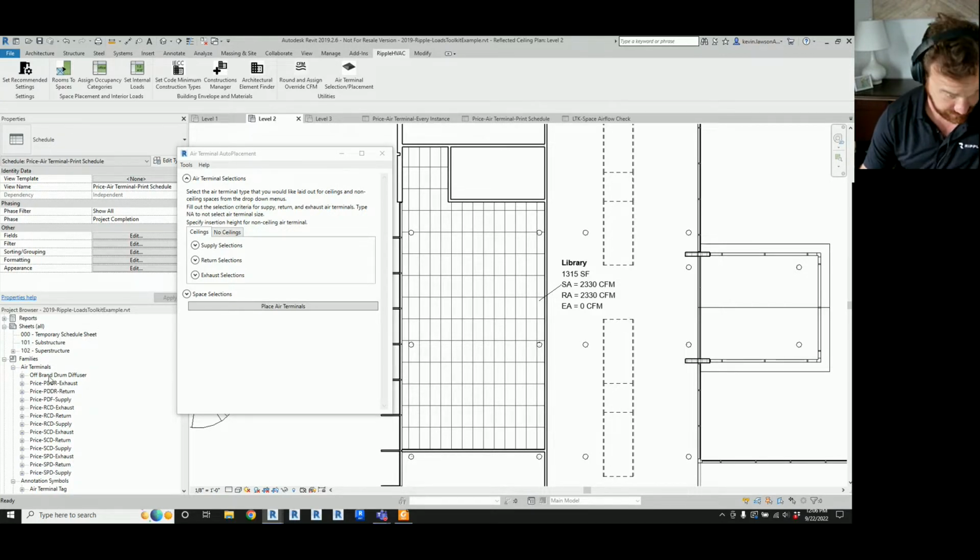The only caveat is you can add to them and you can modify the graphics and everything of them, but I don't change the name or the type names or the shared parameters that are on it, because that's what the tool uses to link the catalog to an actual family that actually goes in your model. So you keep those things consistent and you should be good. But if you want to add or modify, especially the graphics, feel free to modify these however you see fit.